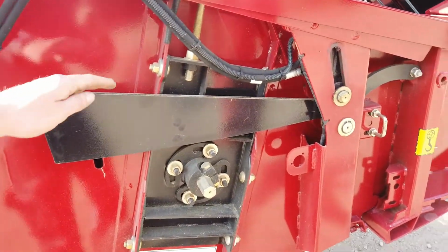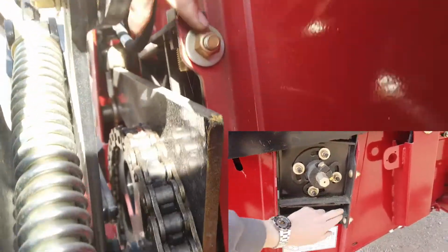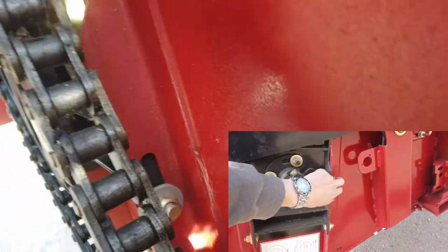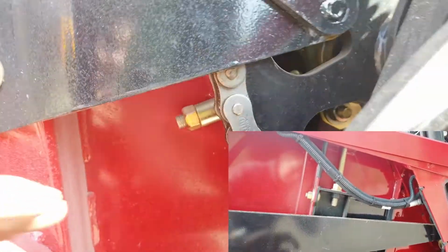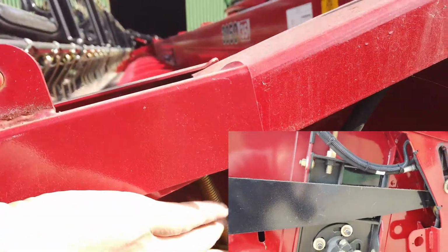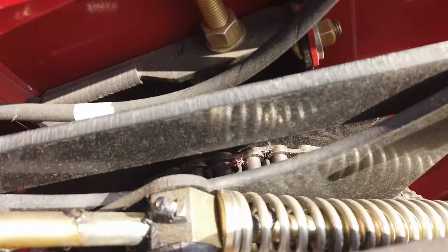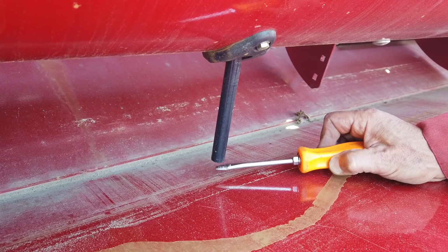The clearance is achieved by the adjustment jacks on either end of the auger and on the 12.1 metre header in the middle as well. Loosen all bolts and use the jack thread to move the auger up and down to suit. Ensure you move it evenly across the full width with equal turns and then check the clearance. When the auger has been adjusted, then reset the retracting tines.